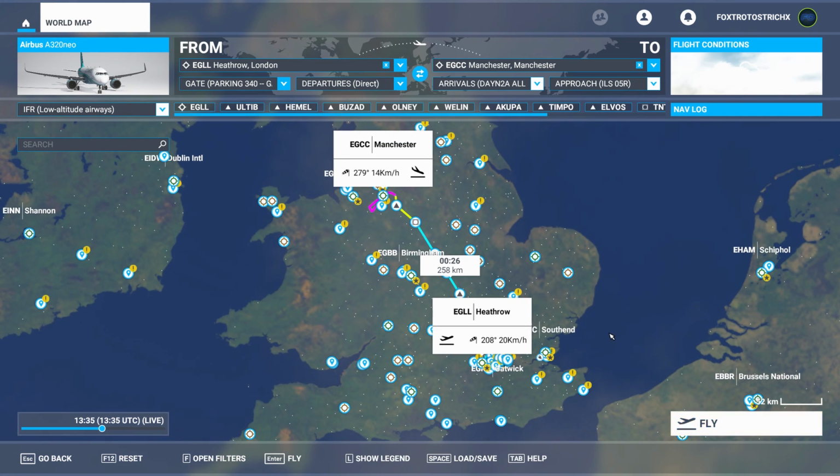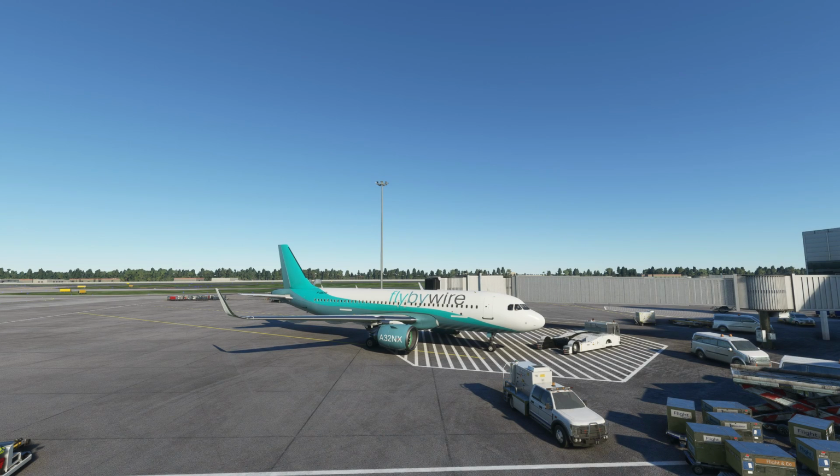Now what we're going to look at today is two different ways you can also set up the MCDU. The first one being manually, in terms of just manually entering the departure airport, arrival airport and waypoints and any airways that you may take, as well as ILS information. And the second way is to actually import the information automatically from Simbrief, which I'll show you later on.